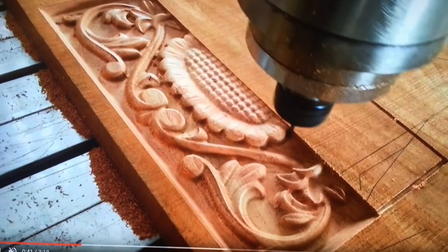One of the things you'll notice though, having a look at this and the detail, there's no internal corners that are square. So even if you look at these corners here of just the outside border, you can see in this area here, there's a little bit of a curved area, okay? Now it's pretty small, but that's to do with that drill bit. So you imagine that drill bit's round, coming down and cutting into that material. So wherever it moves, any internal corner is not going to be a square corner, it's going to have a rounded fillet.